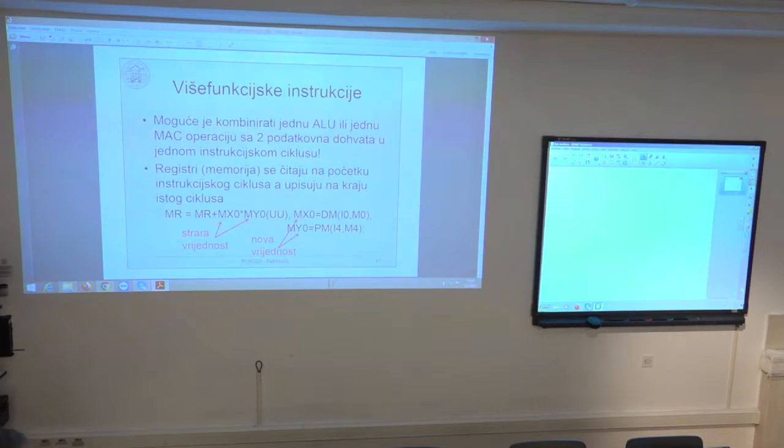And simultaneously performs another data fetch, but from program memory, based on the address in address pointer I4, and fetches this value into input register MY0. And these 2 values are actually prepared for execution of the next assembly instruction. So they are preloaded or prepared as arguments for the assembly instruction that follows.